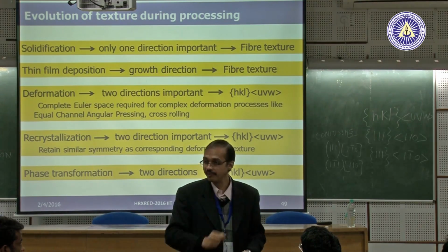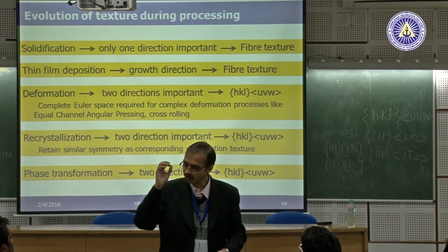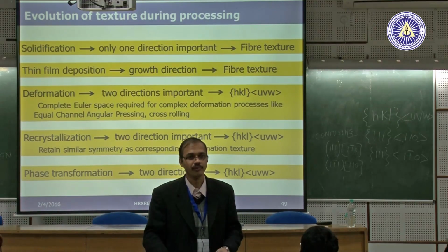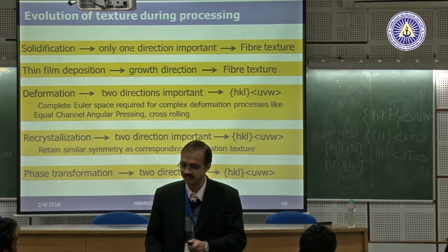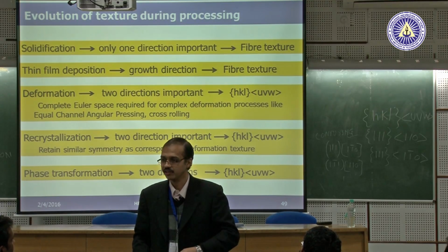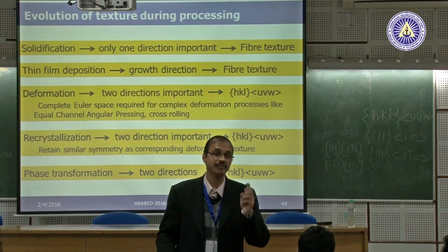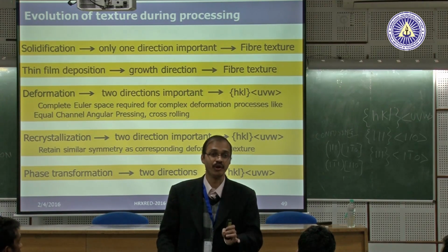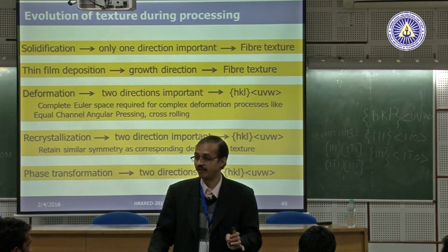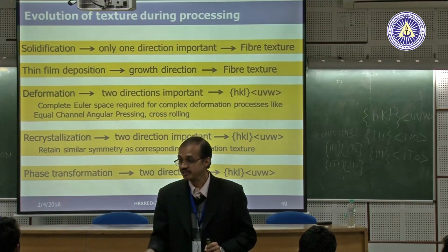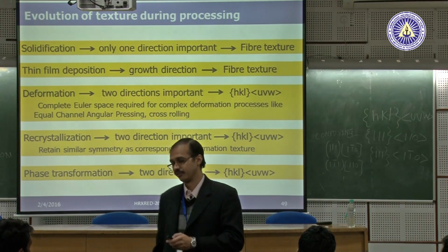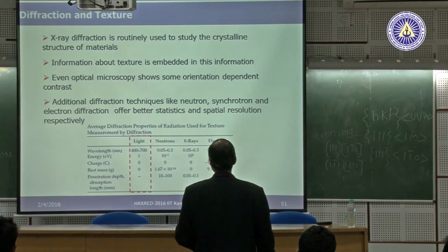People make this mistake when doing microscopy or X-ray diffraction. Today is Monday, so they place the sample this way, on Tuesday they place it that way. Not like that. You have to load the sample exactly the same way, whether you are doing simple X-ray diffraction, SEM or whatever, even optical microscopy. These are small things because the changes are subtle. So I'll spend some time telling you exactly how.